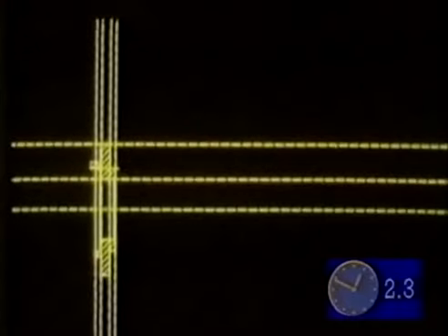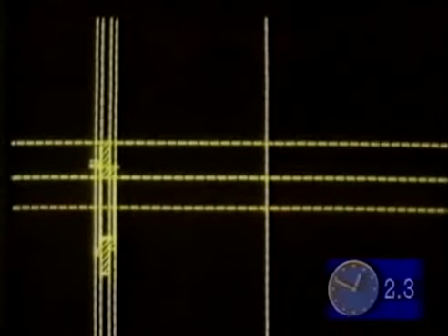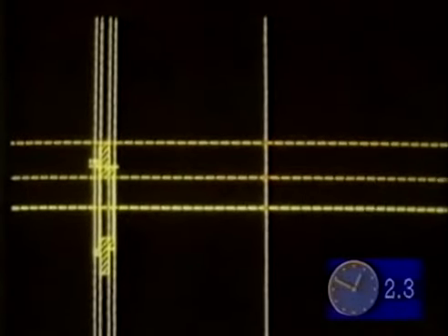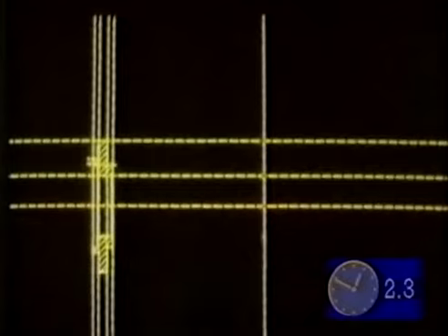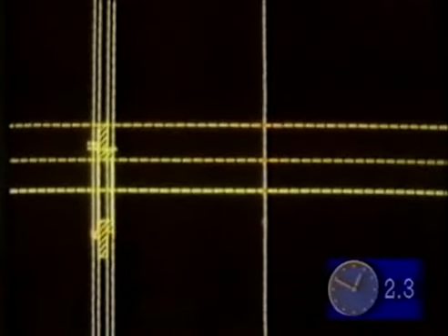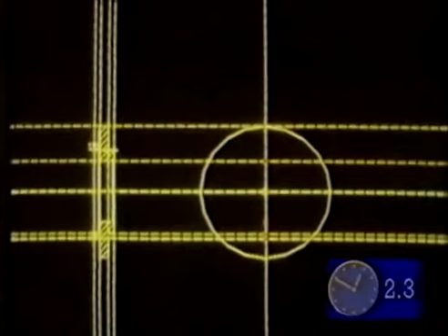Returning to the smaller scale, the geometry of the original temporary construction lines will then enable him to set out the circular front view of the cover. New construction lines identify the center point in this view. The diameters of the various circles required are specified to complete the drawing. The system generates concentric circles which define the outlines of the cover in front view.